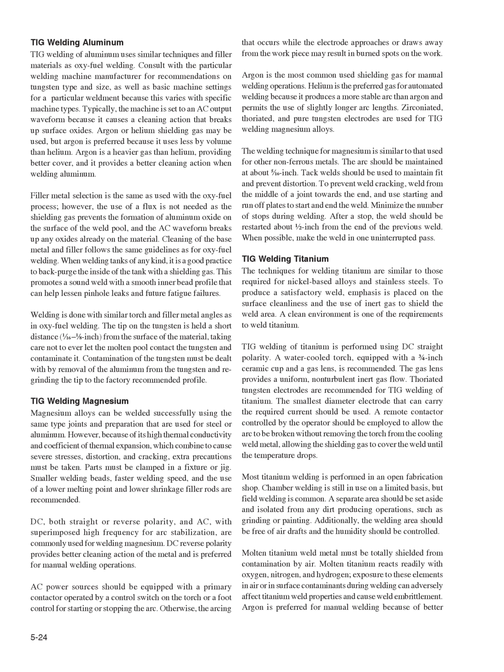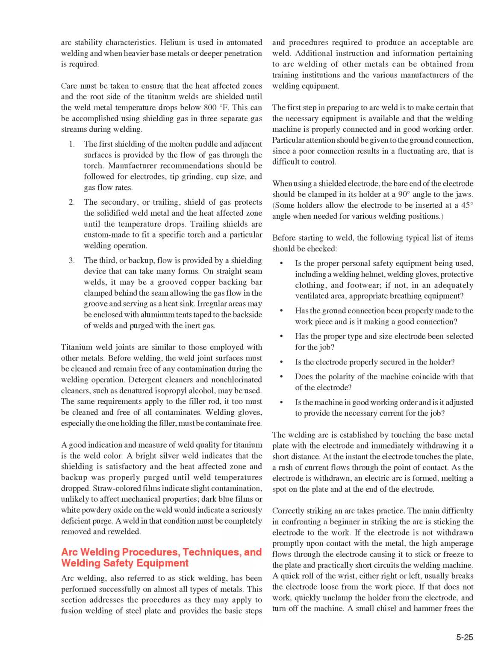Molten titanium reacts readily with oxygen, nitrogen, and hydrogen. Exposure to these elements in air or in surface contaminants during welding can adversely affect titanium weld properties and cause weld embrittlement. Argon is preferred for manual welding because of better arc stability characteristics. Helium is used in automated welding and when heavier base metals or deeper penetration is required.